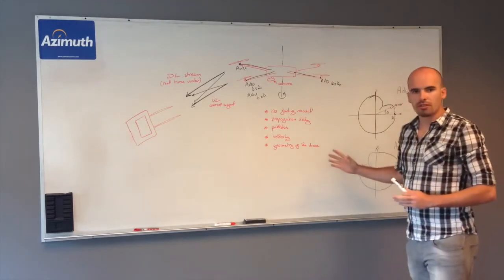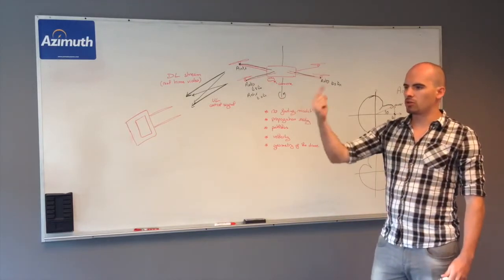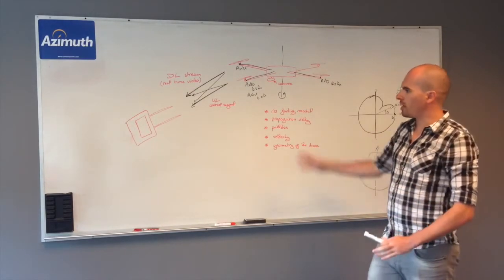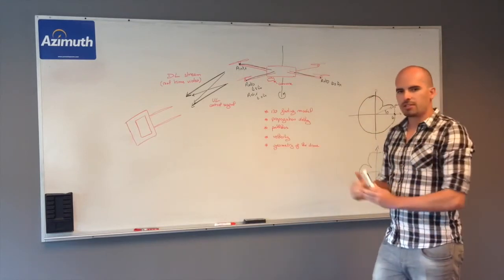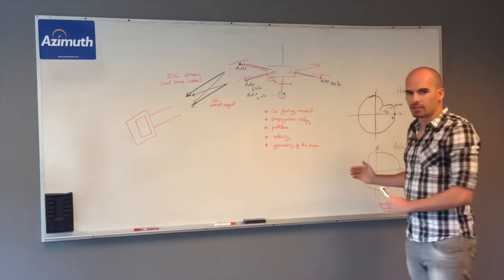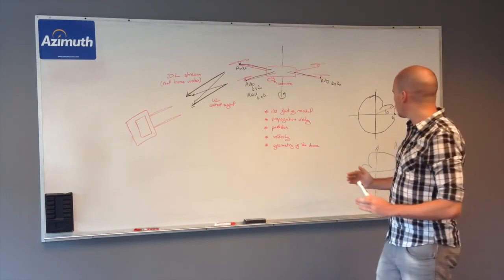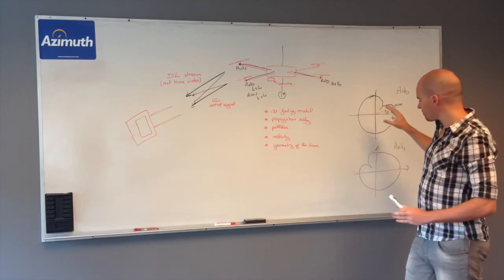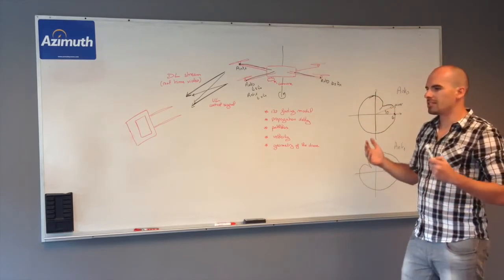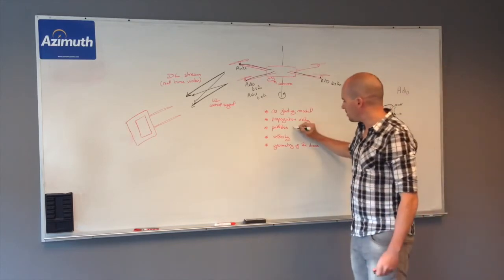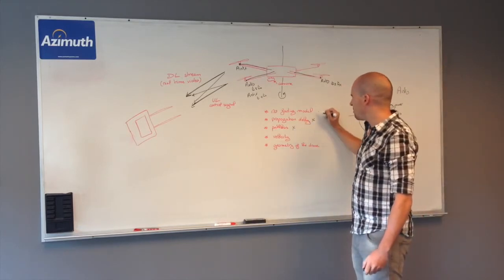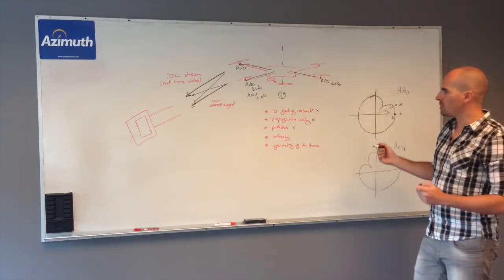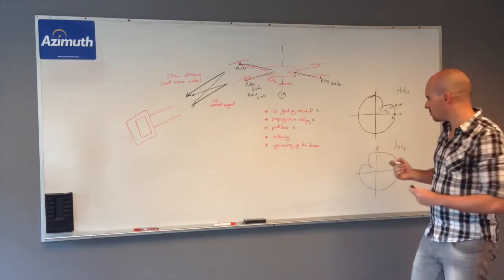We can just go on the field, take a drone, and record some rotation of the drone using our Field-to-Lab technology. We will get the log from the drone and from the controller, feed this into a CSV file, and record those data again. This will already be a very good way to start to emulate this kind of condition and see how the drone performs. Now, if you do that, you will still take into consideration path loss, some propagation delay, but also the fading model, because on the field you will still have some reflection and it won't be like a pure Butler model, for example.